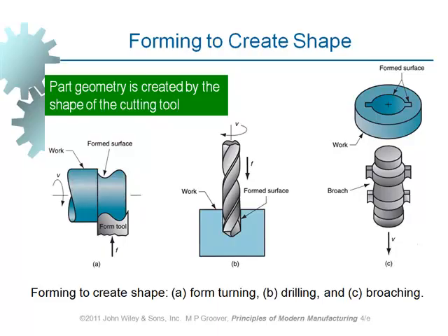But when you move it, they add up to one another, and eventually they take a big cut. Same process is used here. There are a number of cutting edges with different sizes, but the geometry of each one of them is slightly different from the previous one. So every one of them takes a small cut, meaning that in the beginning we've got a hole which is round. The first two cutting edges on the side take a very small cut, and the one after it takes a little bit deeper cut, and eventually what is left is a really deep cut. This is called broaching, and the cutter is called a broach.